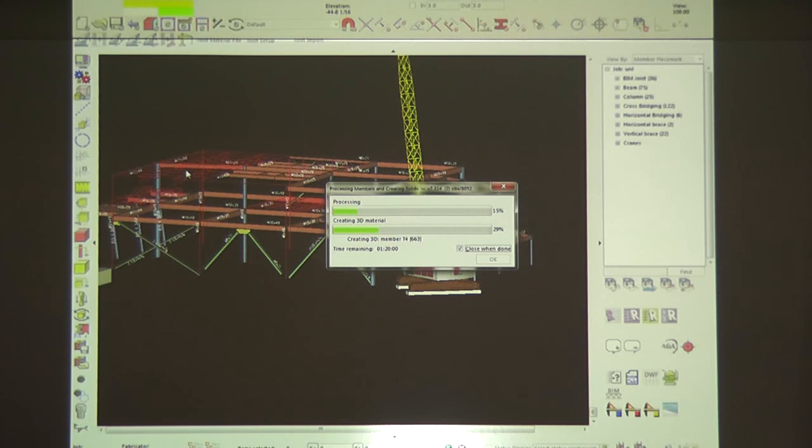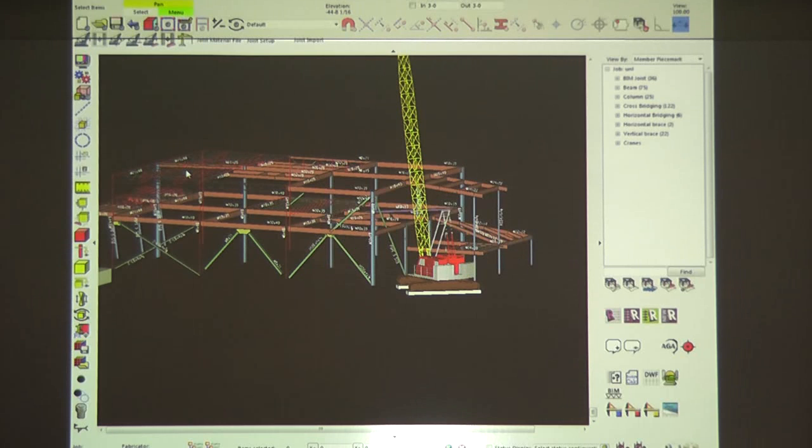So Design Data worked closely with Vulcraft, and you'll see these joists start to be placed in the model. The workflow is, you've seen how we built the model in Revit, we brought it into SDS2. Once it's in SDS2, I take a file from SDS2 and send it to Vulcraft. That file contains the section sizes and the locations in the model. And most importantly, it has something called a GUID on it. As you get more technical, you'll hear this term. A GUID is super important to interoperability because I have to be able to identify